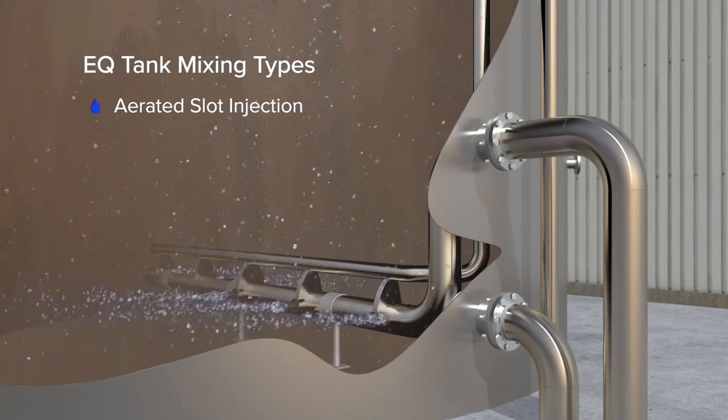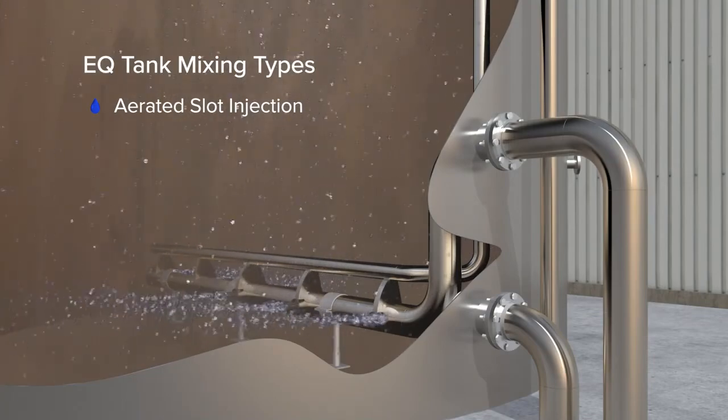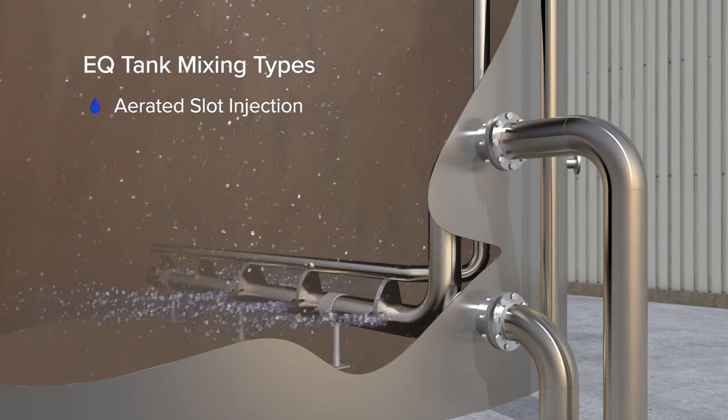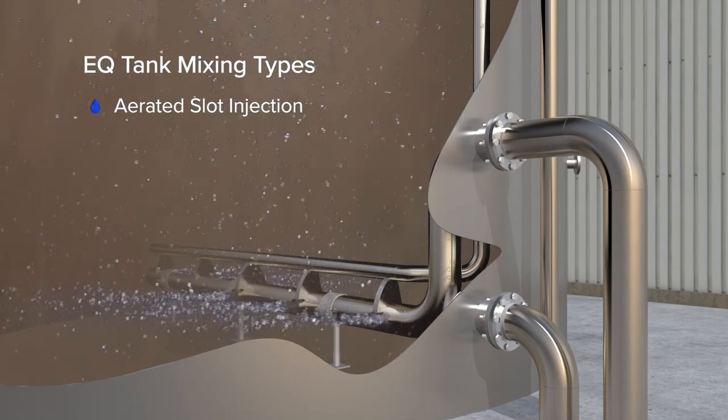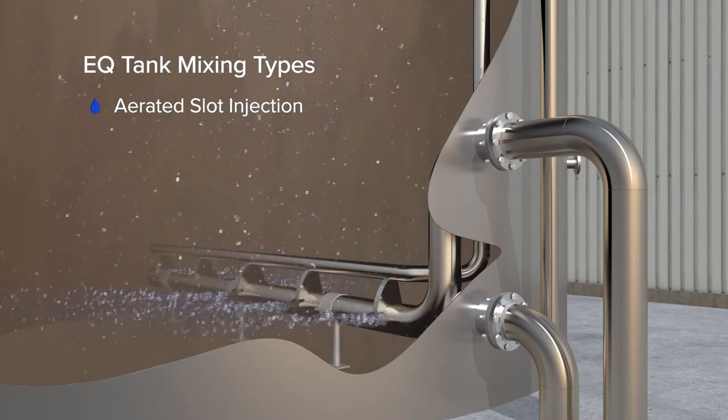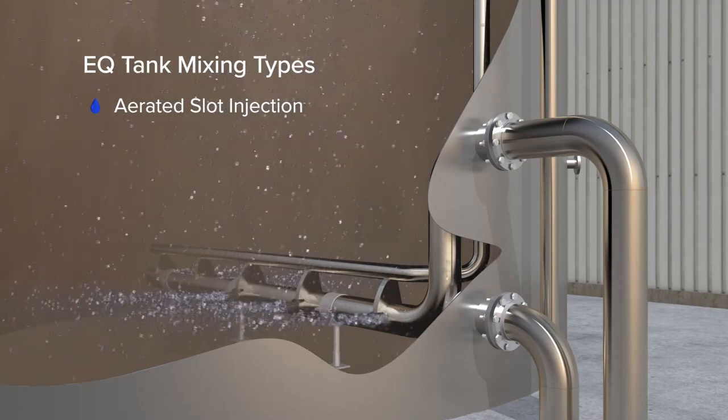Aerated slot injection will use water pulled from the tank, combine it with air from a blower, and recycle it back through the nozzle configuration inside the tank. Mixing can be achieved with or without air to address specific applications.